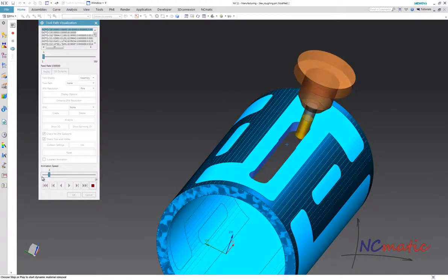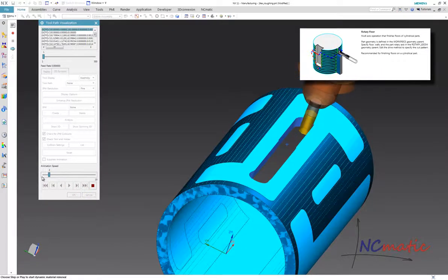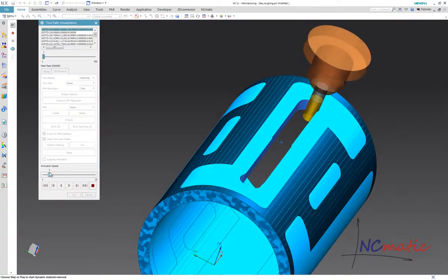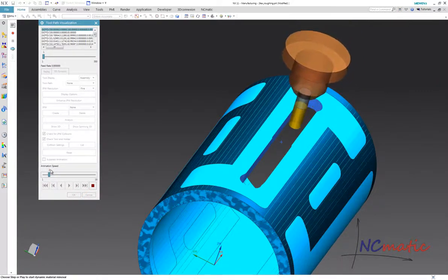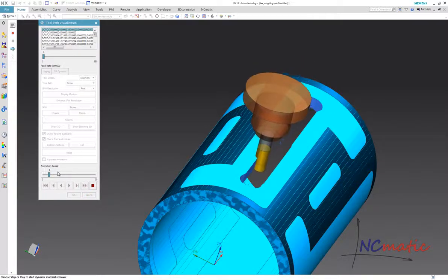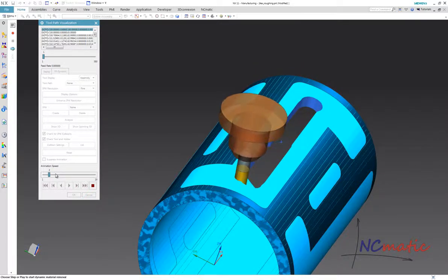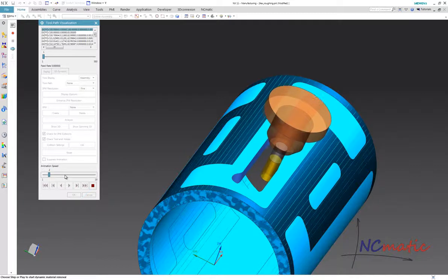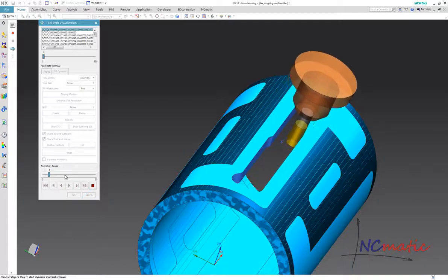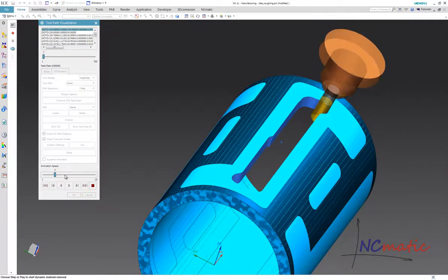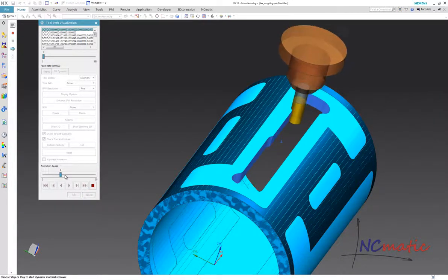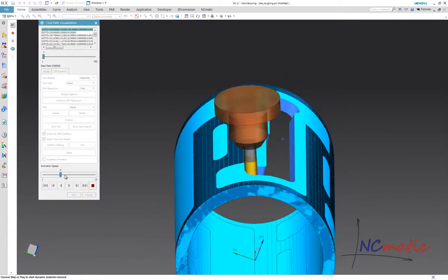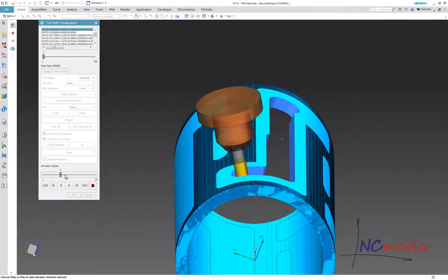We can also use, for example, rotary floor operations dedicated for 4-axis roughing. But rotary floor operations have some limitations in cut pattern types compared to what I did here. Using the approach which I showed you today, we are projecting the planar toolpath towards the center line of the part, which obviously doesn't allow us to machine the part 360 degrees around.